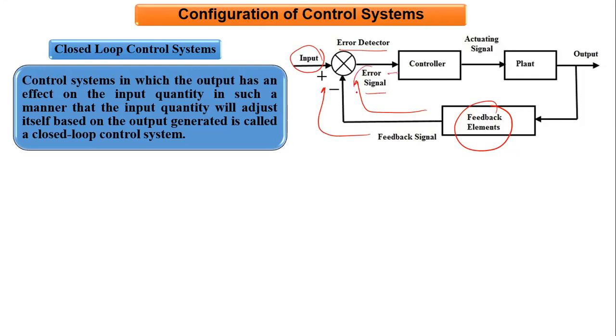On the basis of this error signal, the controller decides the control variable which it generates, and this control variable is sent to the plant so that some of the parameters or processes of the plant can be manipulated or adjusted so that the response of the system can be forced to remain within the desired bounds or limits, right?